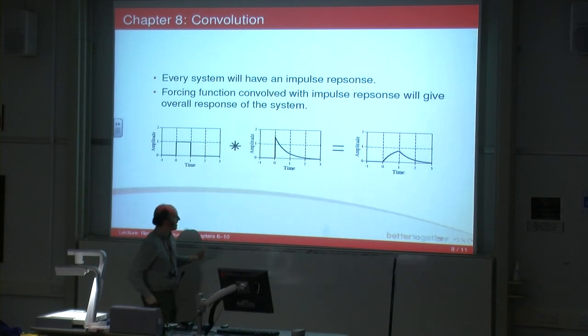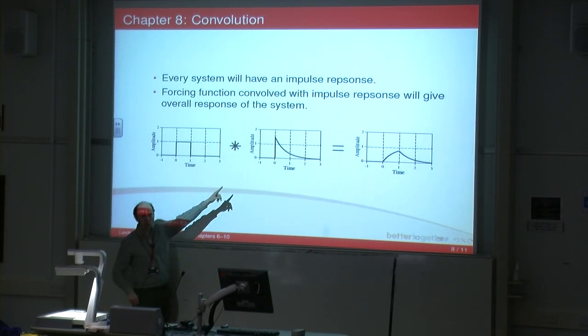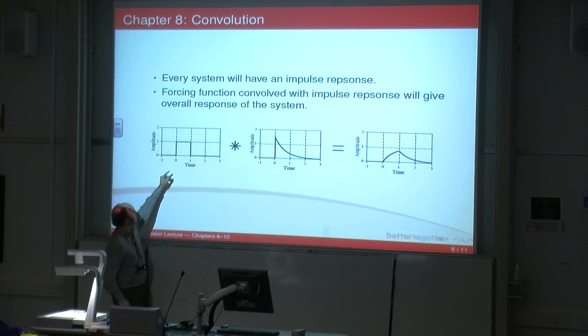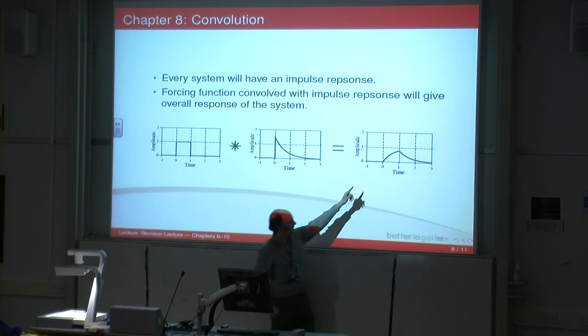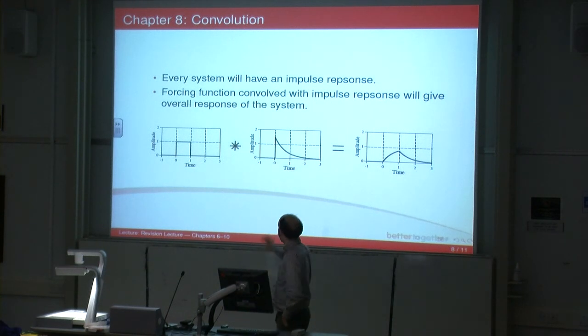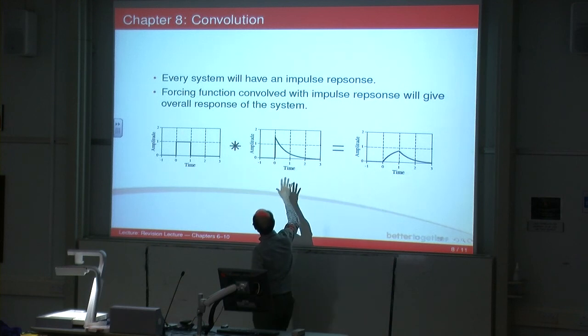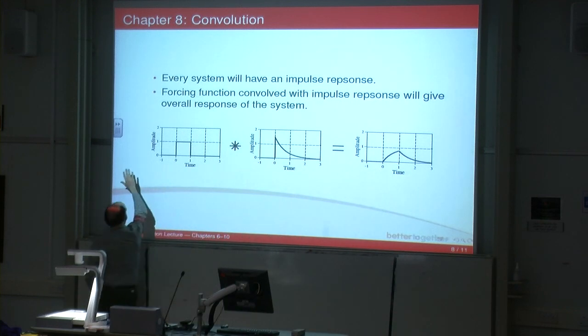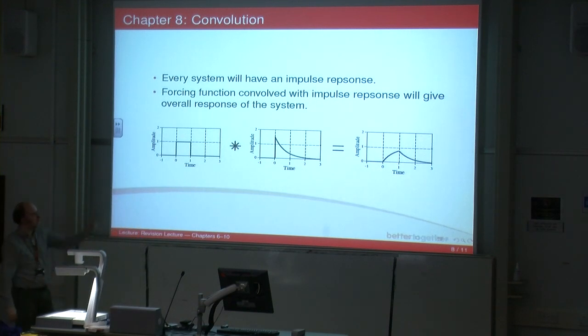So our system, a critically damped system, if you give it a kick, it'll do that. If you give it an input of a certain value, here value 1 for 1 second, then the response is going to look like that, which makes sense. So like I said, you take the impulse response, you flip it over, you move it over here, and you just slide it along the time domain, and you take the integral of the intersecting areas. And you get your response over there.